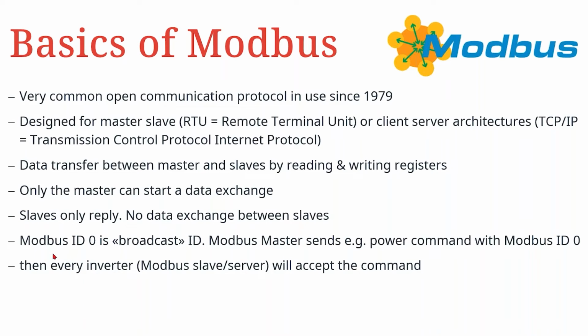And we also have a situation where the master unit has Modbus ID 0, which is a broadcast. That means it sends the signal to all the devices at the same time. So it's a nice, fast way of communicating with the devices.